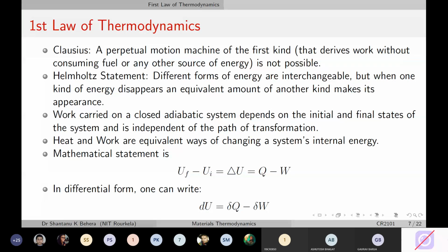It doesn't really matter. Like I said last time, you need to take stock of the sign of dW from a system perspective, whether it's work done by the system or work done on the system, and based on that you'll have to take the sign. So in that sense, the dQ and dW terms are algebraic sums. It is sign agnostic. The definition would be that the combined changes of the heat and work are reflected in the change in internal energy. So that's why I wanted to correct it in the way that you would find easy.